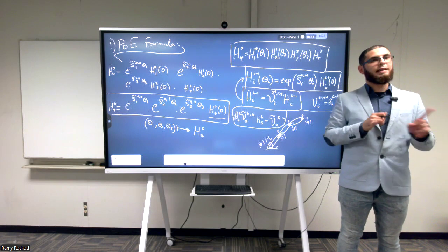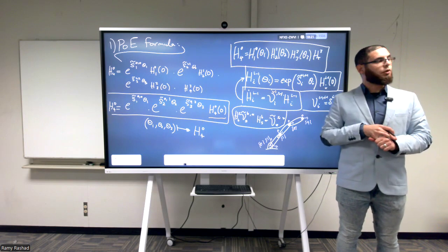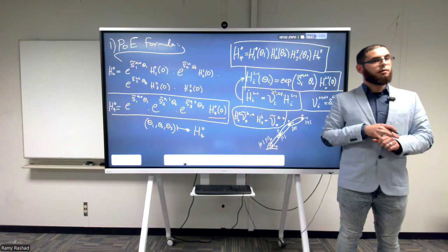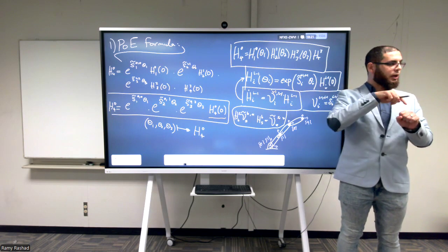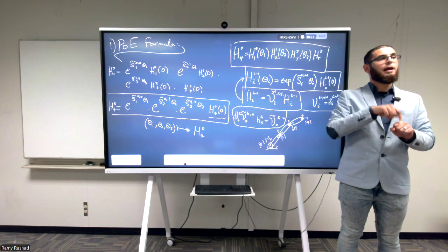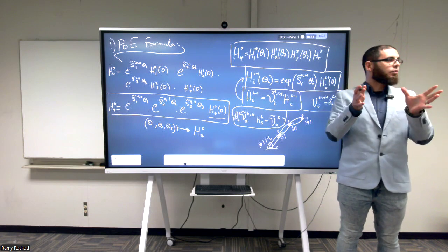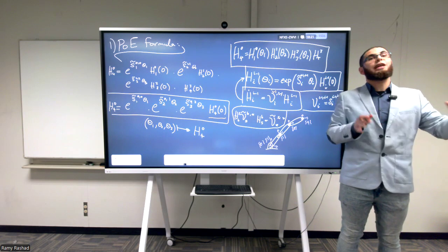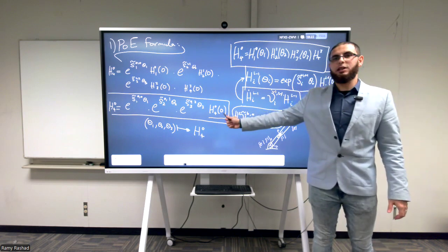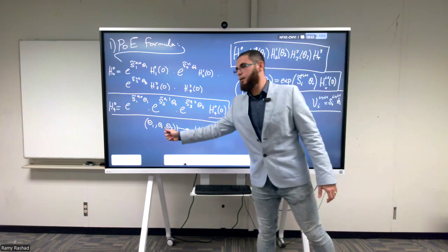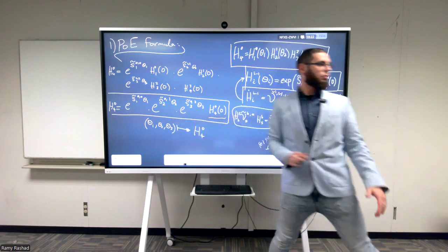The pose of the end effector at time 0, with respect to the reference frame, your stationary reference frame, at which scenario? At the initial condition, at your home configuration. The home configuration here is when you choose theta 1, theta 2, and theta 3 equal to 0.